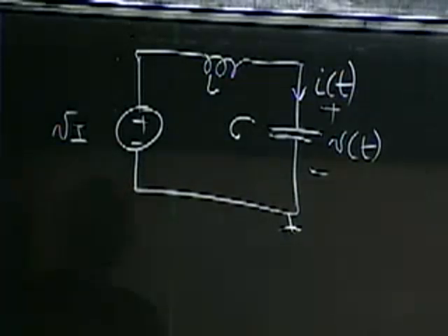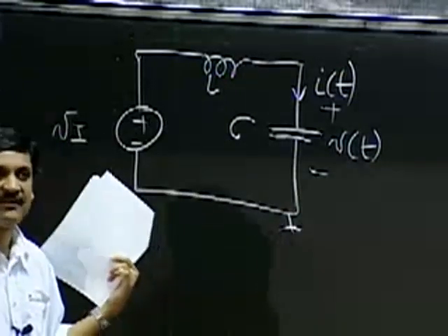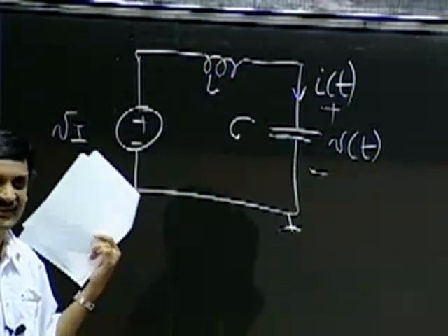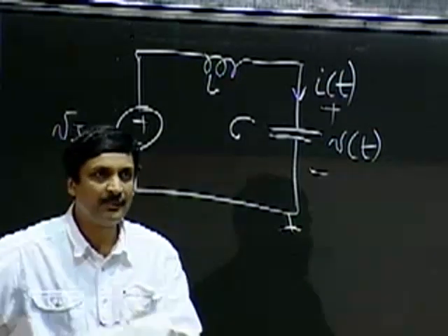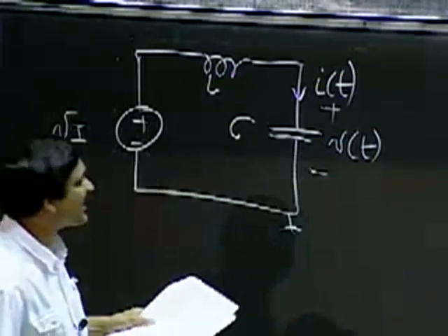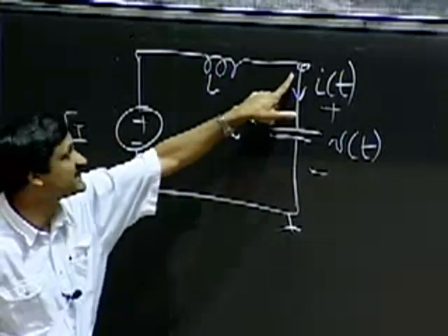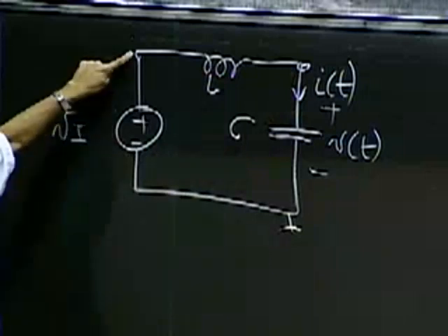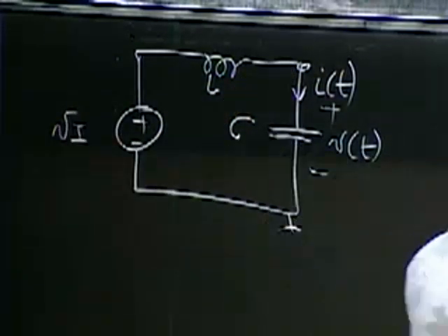Okay, and we're going to proceed in exactly the same manner as we did for first order differential equations. So write the equations down and just go down the same set of steps, but get to someplace different. So we're going to start by writing the node equation for this node here. That's the only node for which I have an unknown voltage. The node here is VI, so I need to find this. There's just one unknown node voltage. And I'm going to need some element laws.